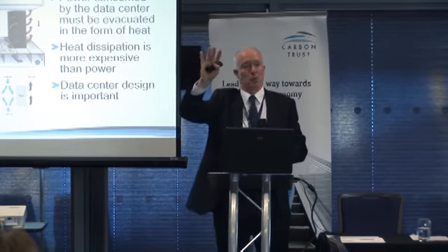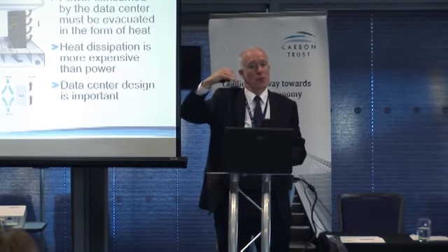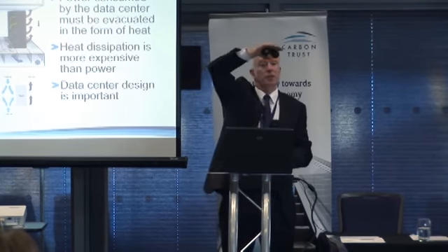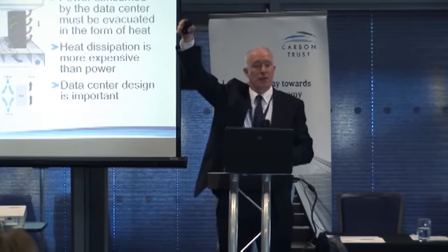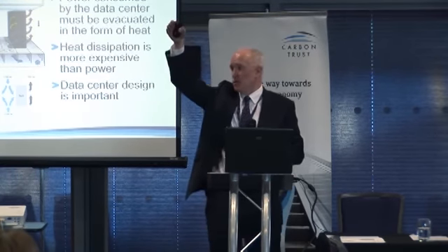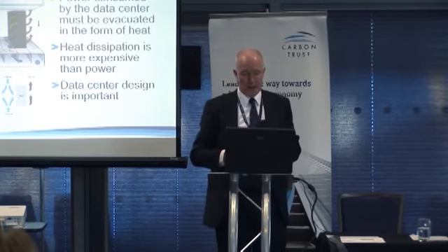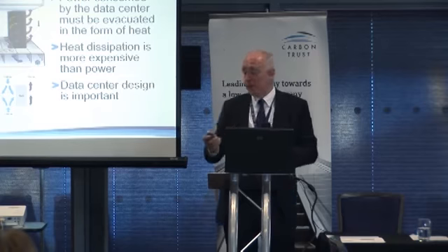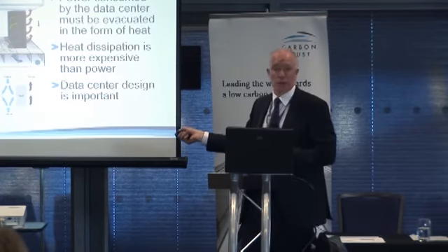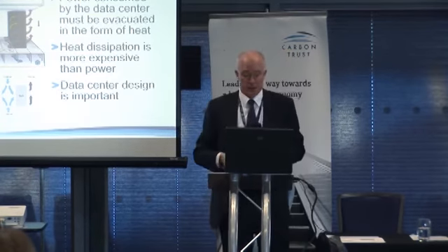We can put up portable partitioning; we want to try and make more use of that. And perhaps if you've got the ability to return that hot air onto the top of the unit, then that's what you should be trying to do. So there are practical limitations depending on the sort of kit that you may have within your equipment. You may not have the advantage of cold air distribution in the floor and hot air distribution in the ceiling voids.